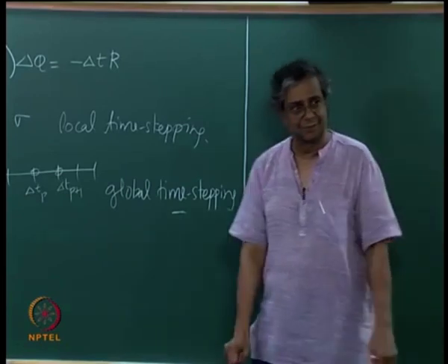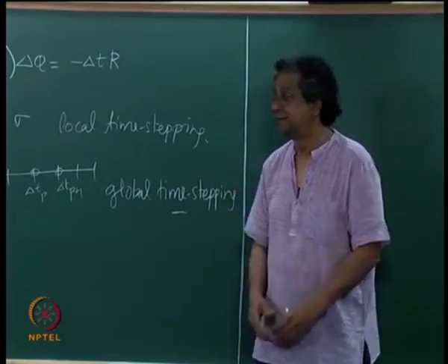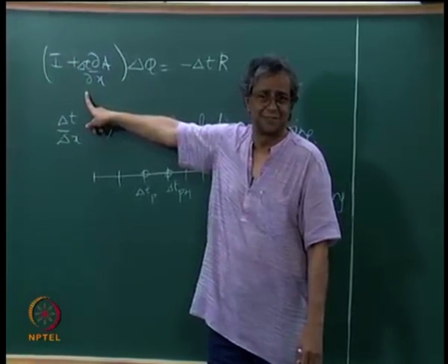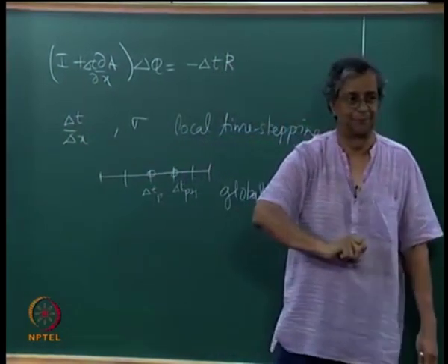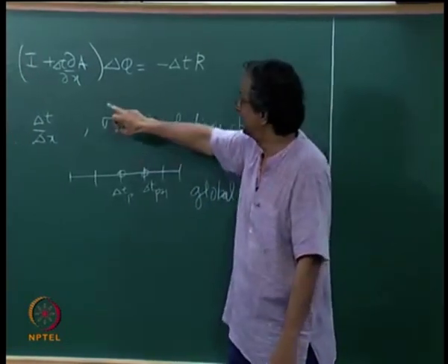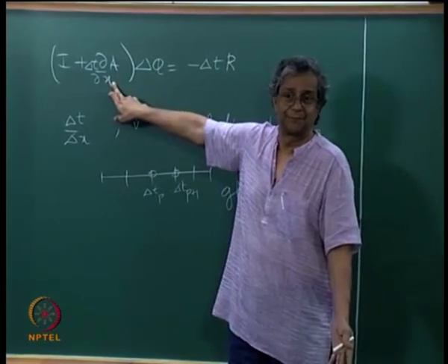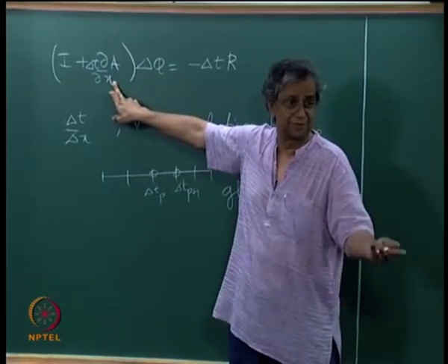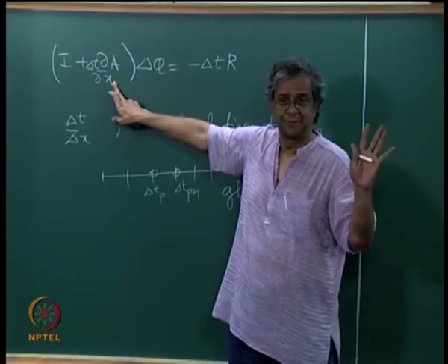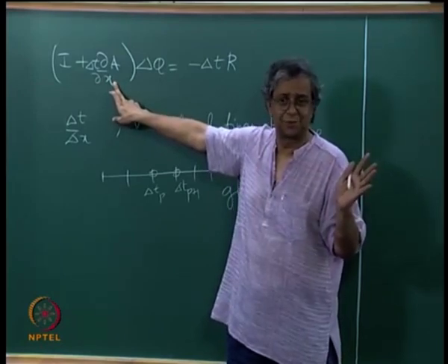The other thing, remember, I only want to get to the steady state solution. So we talked about fancy things that we could do, approximate factorization and so on, but there are simpler things that you can do. Okay, how many terms does the flux Jacobian have? Flux Jacobian is A. It's a 3 by 3 matrix. You can imagine if the problem was in 3 dimensions, if you are solving the 3-dimensional Euler equations, it's a 5 by 5 system. The expressions aren't that great, right? They are pretty expensive to calculate.